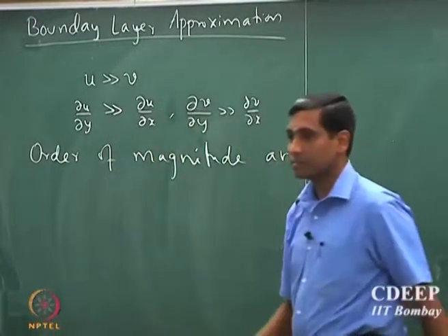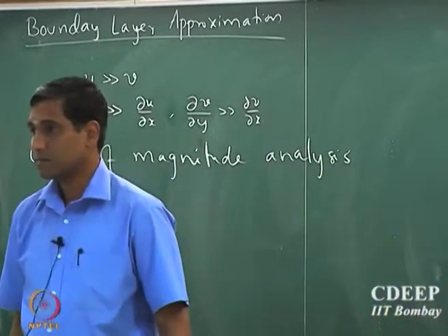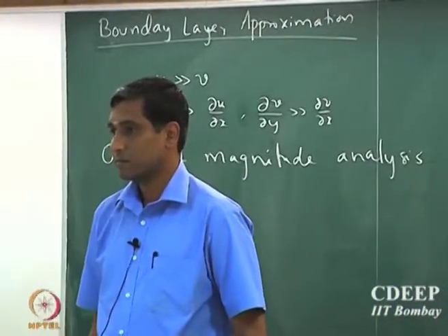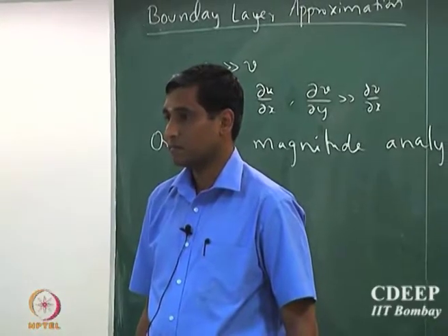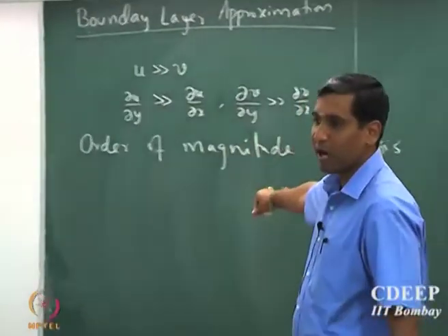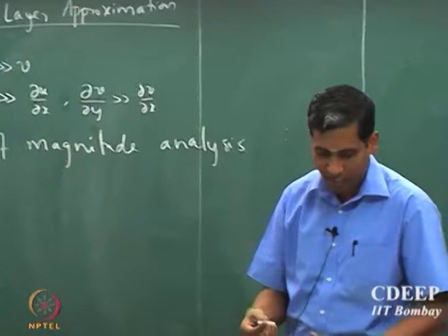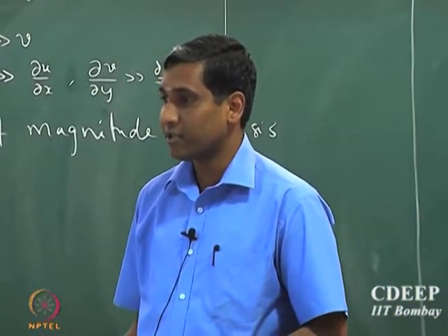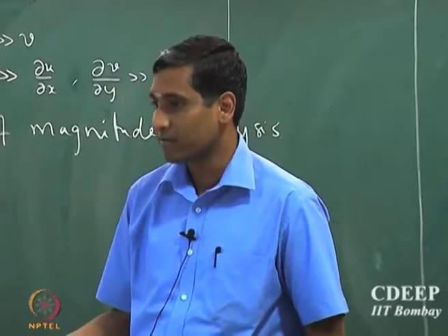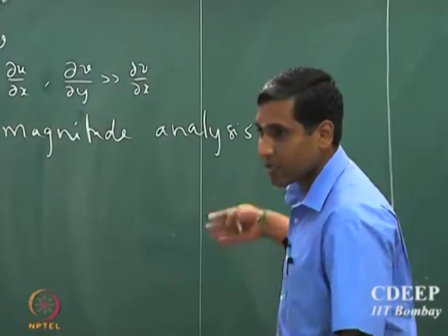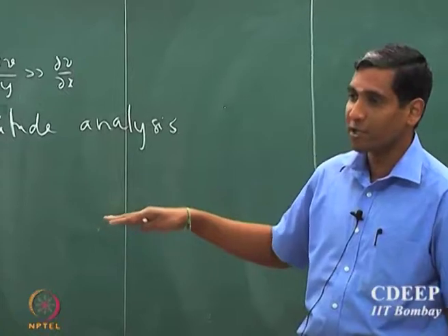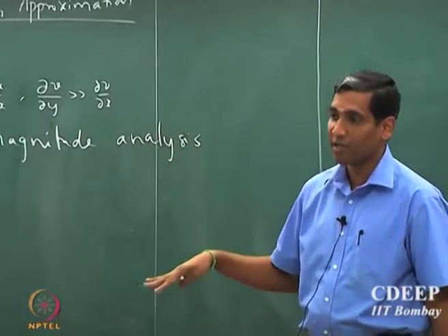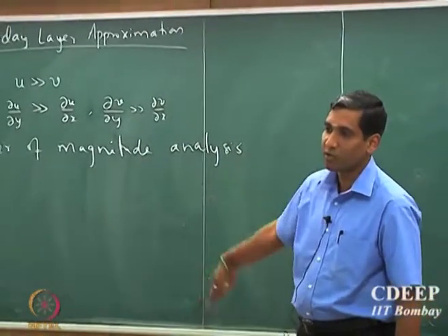Let us assume for now, you will actually see it, that if the forced convection flow rate is significantly larger, then body forces don't play much role here. Body forces play an important role when you have natural convection, not in these kinds of forced systems.